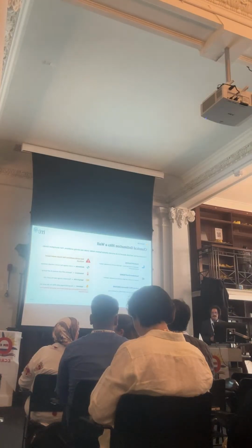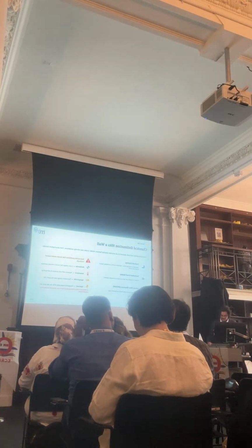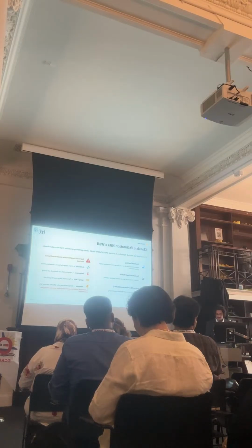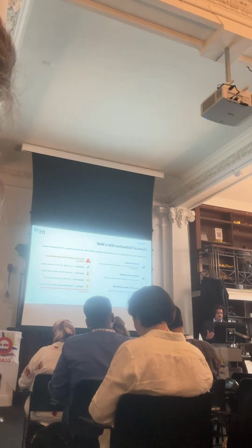In classical estimation, there are three main families: Coulomb counting, which integrates current but drifts as errors accumulate; equivalent circuit models, which are simple but hypersensitive to their parameters; and Kalman filter observers, which are accurate but depend on an accurate physical model and careful tuning. They share one crucial weakness. They assume that you have a good physical model of the battery. And in the real world, that assumption, of course, breaks, and that causes some errors.